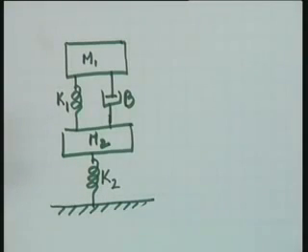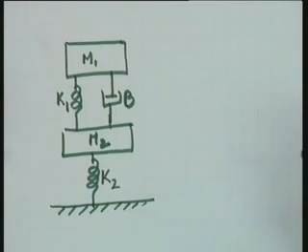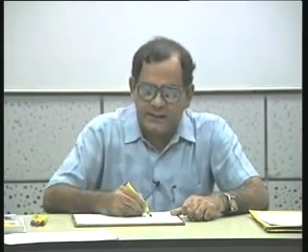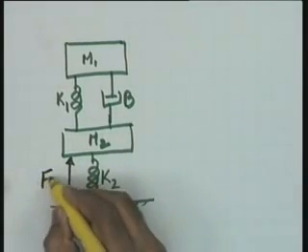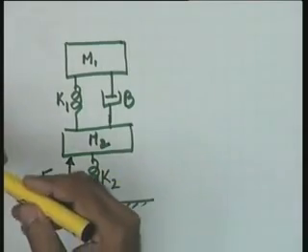Under consideration is the study of the effect of the road surface variations. It means I am interested in the study of vertical motion of the vehicle. The vertical motion of the vehicle will come as and when the bumps come on the road or there are other disturbances, the roughness and other things. So, as far as this attribute of study of the vehicle is concerned, the input is a vertical input, which you can definitely declare to be the disturbance input. So, this is the disturbance input to the system.